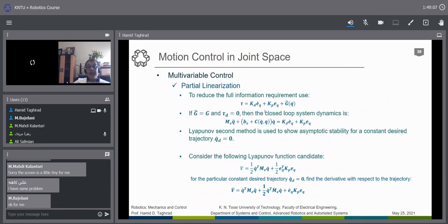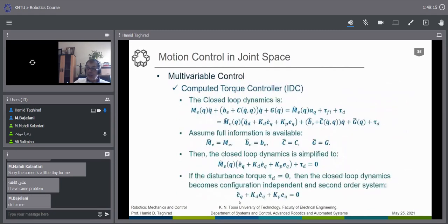You tune depending on how much effort you can give to the system. You can consider this dynamic equation. The relation between Kp and Kd, you use somehow to have a zeta equal to 0.707. You have a Butterworth relation, or a very good relation in terms of the transient. So you keep the ratio between Kp and Kd to have the zeta assigned to the desired value that you wish, and then you increase the gain, both of them.